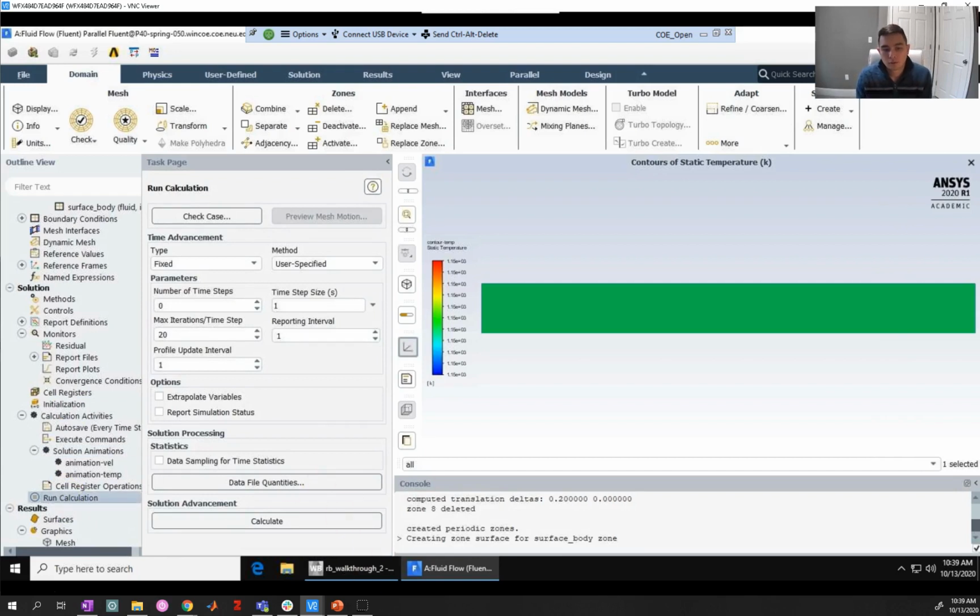The last thing we have to do is run our calculation. For the run calculation, I want to make sure that we get nice resolved, converged results. But what we'll notice is that your ability to get resolved results changes over time. So we're actually not going to take too many steps, but we are going to allow a huge number of maximum iterations just so that you can get a feel for how the amount of iterations changes as the dynamics change.